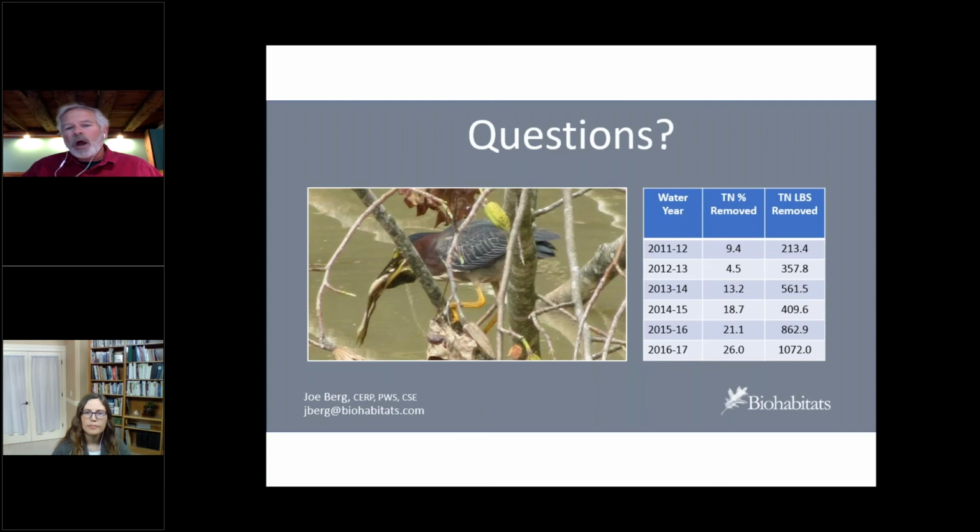This is not washed concrete sand or any kind of pure material. This is material that's rapidly or easily available. We call it material of opportunity. We've talked to some about using gravel from old roof treatments, where in the not too distant past, you'd put your tar paper down, and then you'd put a 4-inch or a 6-inch layer of gravel over top of that, so that the sun wasn't destroying the integrity of your roof.